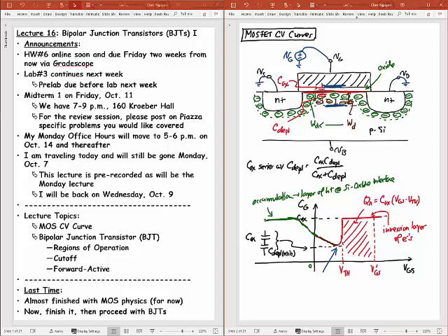This charge is changing because I am putting positive charge in and out due to the polysilicon, doped polysilicon, almost metallic type layer there. So the capacitance that I'm getting here is really between these two spots right there if I'm looking just at that particular point. Okay? And so in the end, the capacitance that we're looking at is consistent with the classic definition of capacitance.